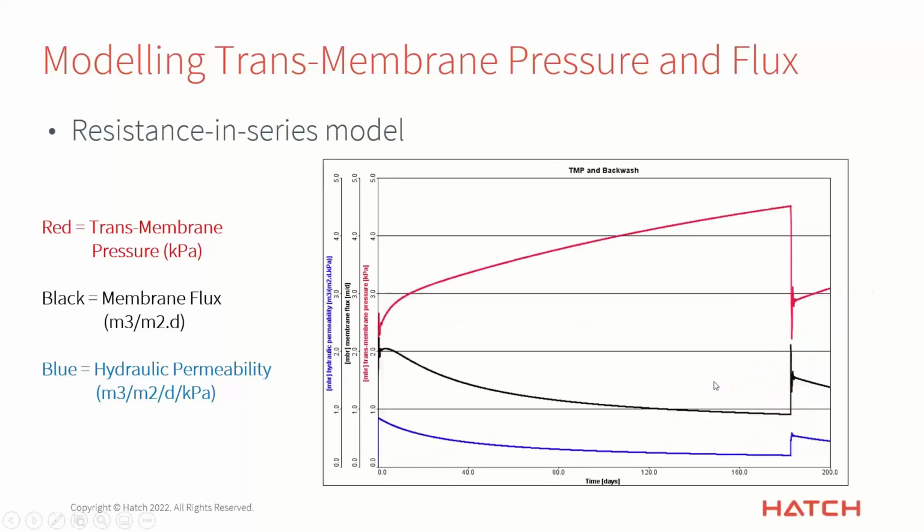Okay, so then I ran another simulation. Both of these, by the way, were with the layout that I just showed you earlier. This is actually 200 days here that I was running. So again, the backwashing was happening all of those 200 days and so on. But I wanted to run a long one so that you could see how the transmembrane pressure increases over time in order to maintain a reasonable flux.